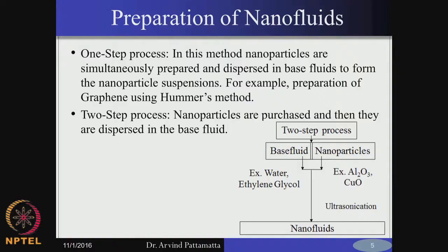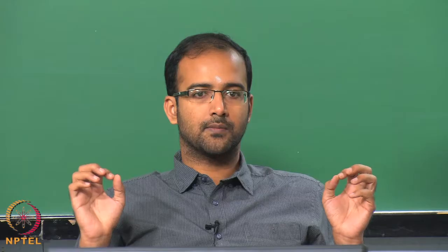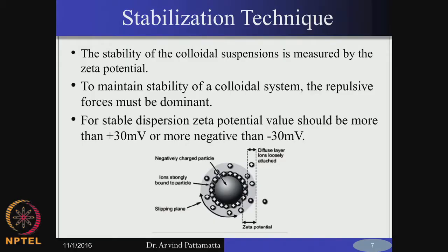So, therefore, the first step is synthesis of nanoparticles, second step is, you mix nanoparticle with the fluid and then you do what is called sonication. That means you basically stir it at very, very high frequencies, ultrasonic frequencies for considerable amount of time, so that as much as possible your suspensions become very stable, okay, and they do not sediment. Okay. So, there are also chemical ways of making it stable, like modifying the pH. The other attractive way is looking at the potential of an EDL.